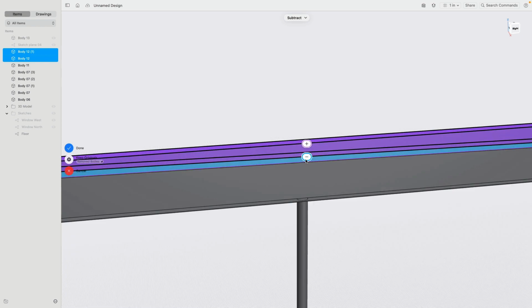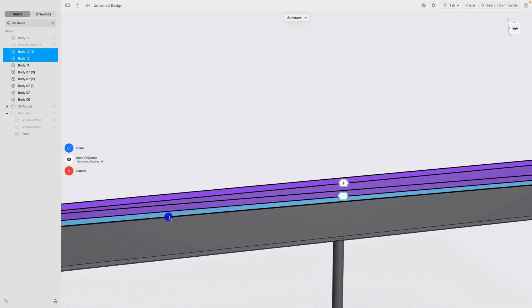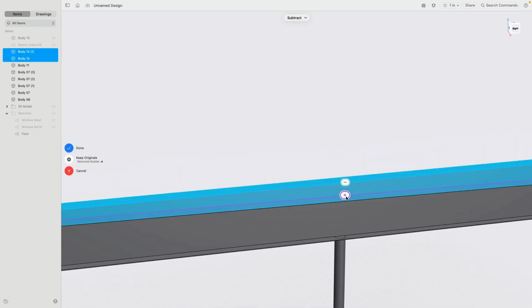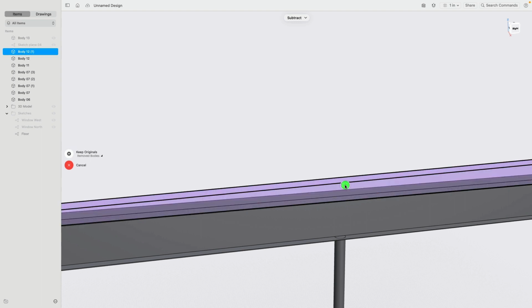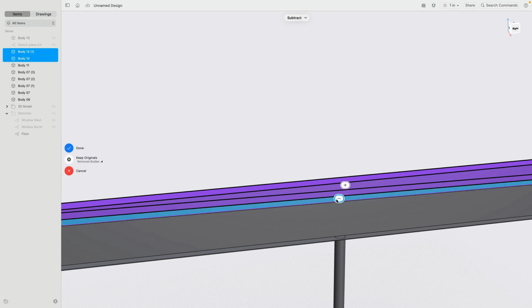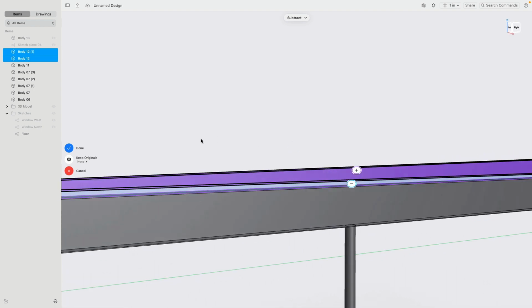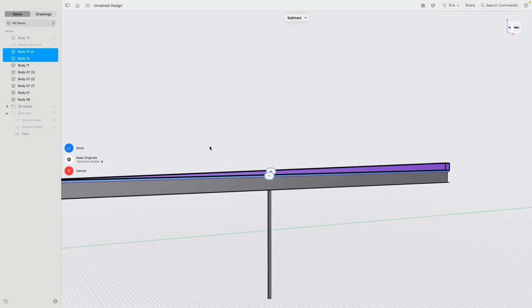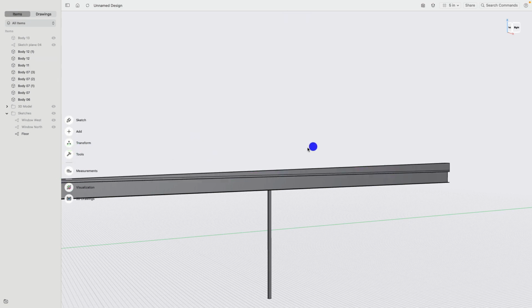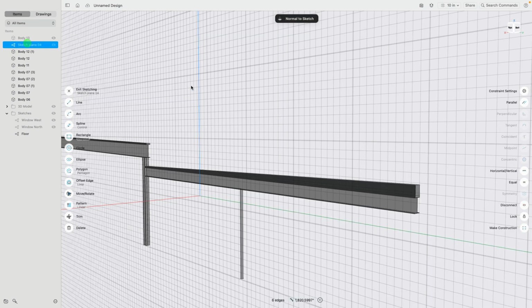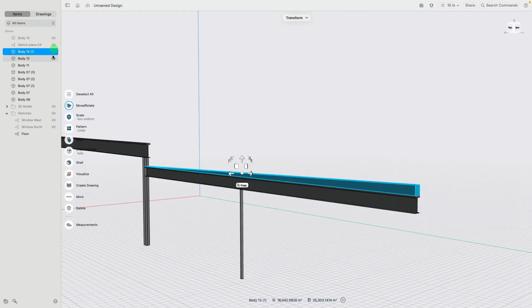from the bigger one, the blue one, I want to remove this, remove bodies. Okay, what does this color mean? Basically, this is my target, and this is my tool. And then when I turn this off, you see that's empty because the lower piece will be removed, but I want to keep this tool. So it's kind of like the power tools in SketchUp. The horizontal wooden piece removes its volume from the bigger magenta piece, and we end up with both as an end result. There. Awesome.